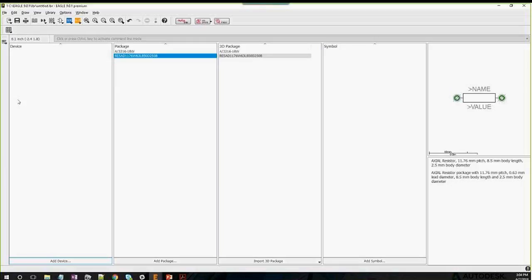The other thing that we want to do here is the question: how do we create non-rectangular and non-circular pads? It is possible in Eagle, and it's done through arbitrary pad shapes. Basically the way that works is you start with one of the default pad shapes, be it a VIA or an SMD, and then you use a polygon to form whatever outline you need.